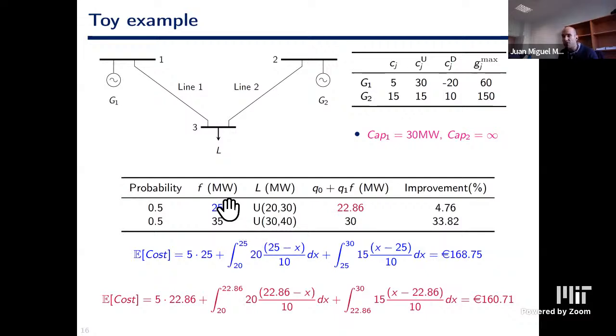Note that if the context, that is the point prediction of the load at the forward stage, is 25 megawatts, the upcycling rule is telling us that it is better to underestimate the system load in the forward market so that we can reduce the need for downward regulation from unit 1, which is very expensive.